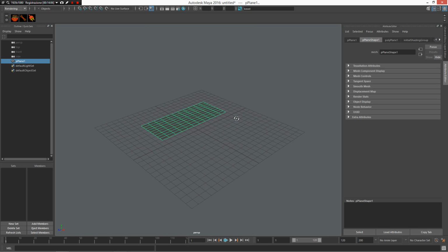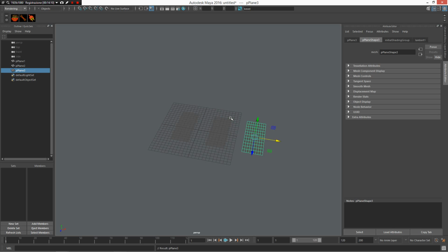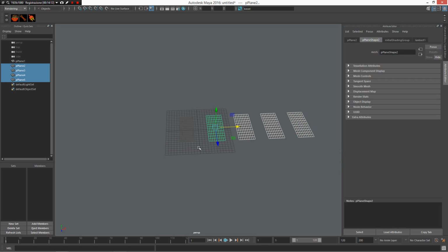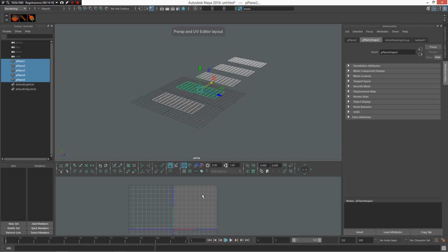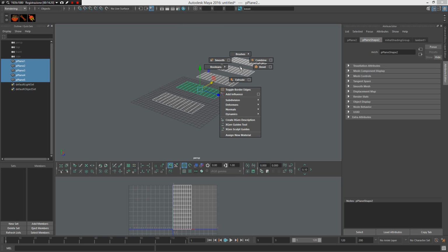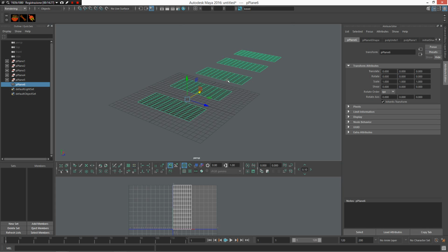All right, great. Shift D. Alright, great. All these objects use the same UV, of course. If I go under Alt 4, I need to select all of these. Another time use my marking menu, and I want to combine it. Okay. Now all these objects are combined together using the same UV.